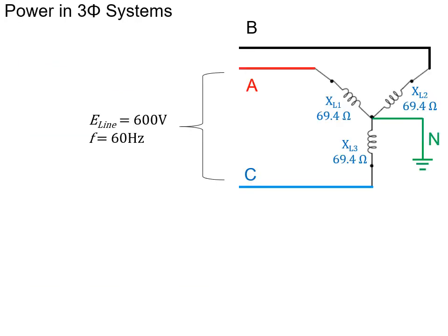So let's go back to our sample Y problem and calculate out the inductive reactive power in VARs. Earlier, I had said that the phase voltage was 347 and the current was 5 amps. And within a reasonable margin of rounding, that is acceptable. And 347 is considered the nominal three-phase voltage for 600 volts line, which did result in 5 amps.